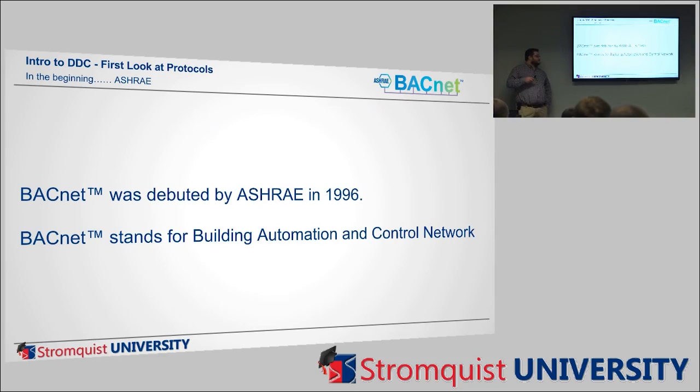All right, so LON really was the early adopter, like I said, because they took the hardware approach to things. It was a lot easier for controls manufacturers to say, I'm just going to buy your chip that you did all the development for, put it in my equipment, and now I meet an open protocol. But like I said, one of the disadvantages to LON was that it wasn't just developed for the building automation industry. It's developed for power line grids. It covers a lot more things, and that's why it's more complicated. And it's more of a European standard too. So there's a lot more involved with LON because they tried to be a bigger umbrella.